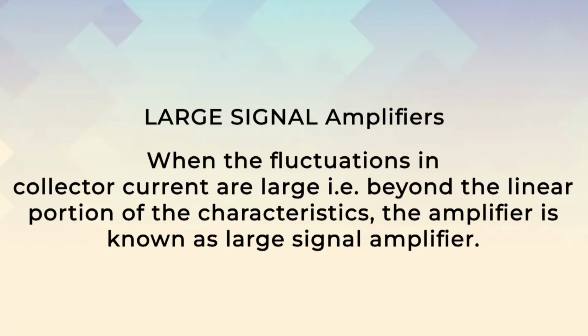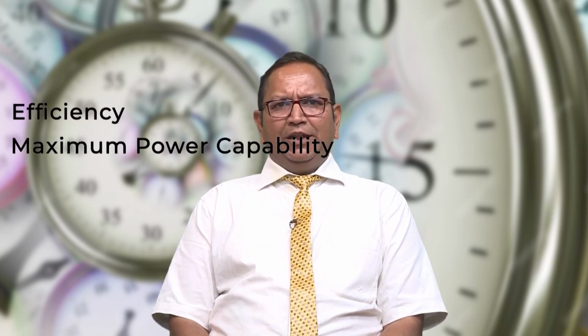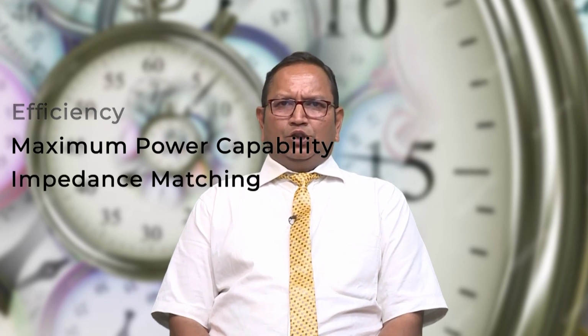Now, the second one is the large signal amplifier. When the fluctuations in the collector current are large, that is beyond the linear portion of the characteristics, the amplifier is known as a large signal amplifier. A large signal or power amplifier handles relatively large voltage signals and current levels. The main factors of this large signal amplifier are efficiency, maximum power capability, and impedance matching to the output device.